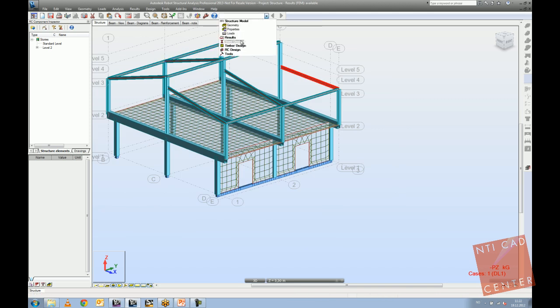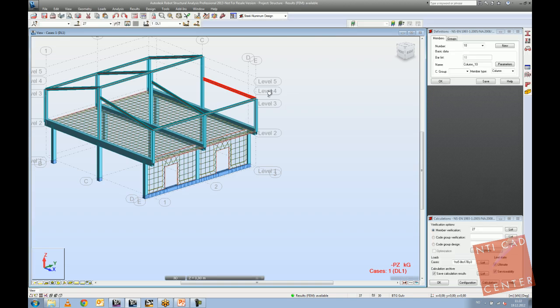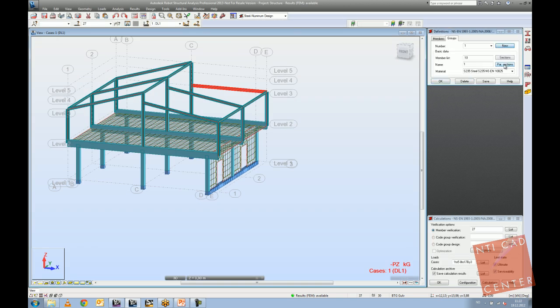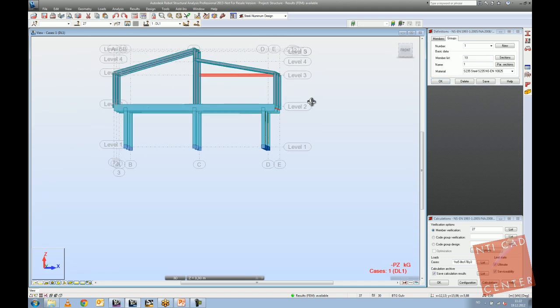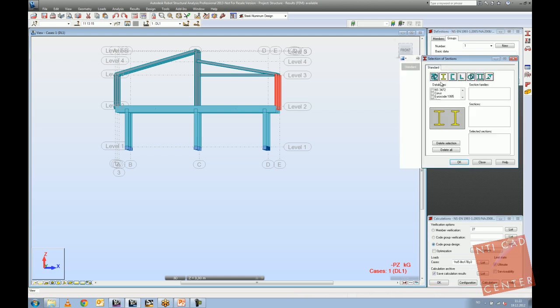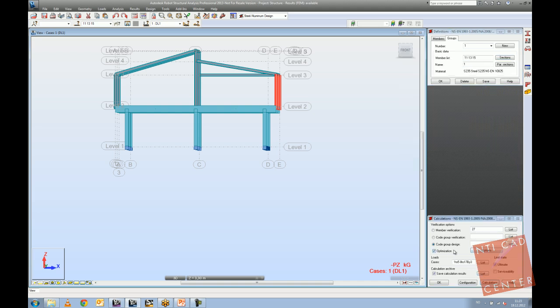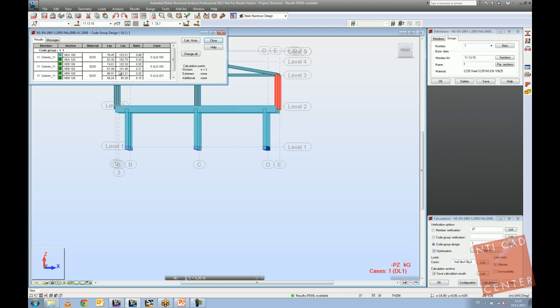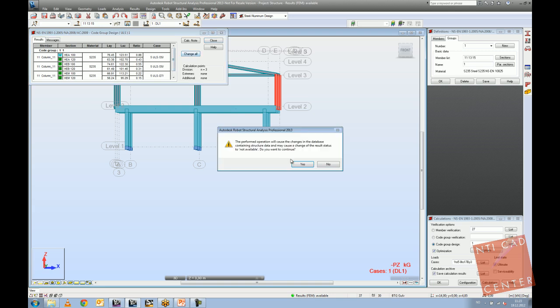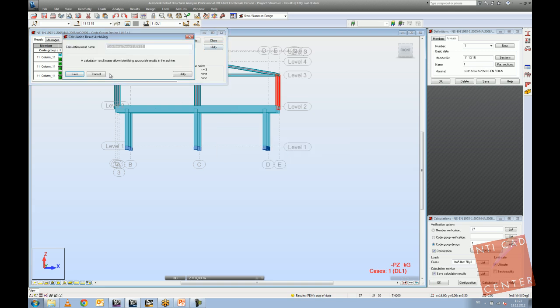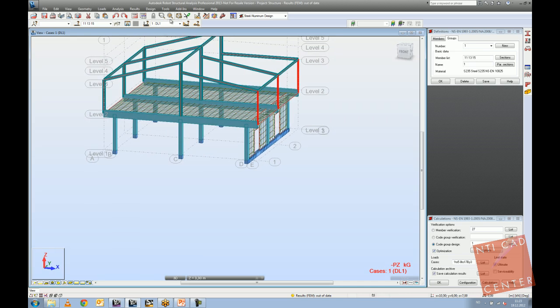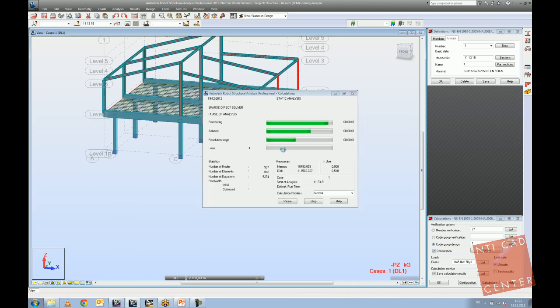And let's move, for example, to steel design, steel aluminum design, and maybe create a new group, specifying some member numbers. For example, these columns should be the group, and for that group I would like to choose from HEAB profiles and optimize that group by weight. Run the calculations. HEA100 is the optimum one, changing all to quite smaller profiles. So the profiles are updated. Recalculate it again.